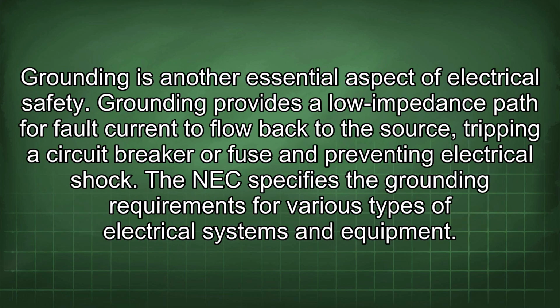Grounding is another essential aspect of electrical safety. Grounding provides a low impedance path for fault current to flow back to the source, tripping a circuit breaker or fuse and preventing electrical shock. The NEC specifies the grounding requirements for various types of electrical systems and equipment.